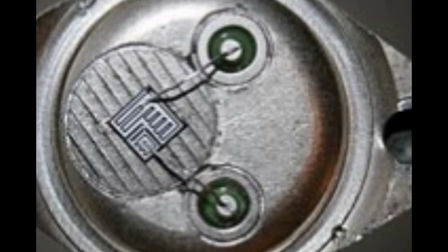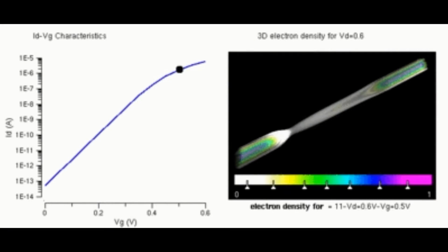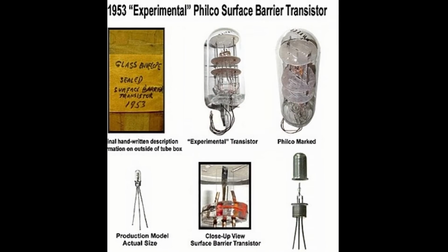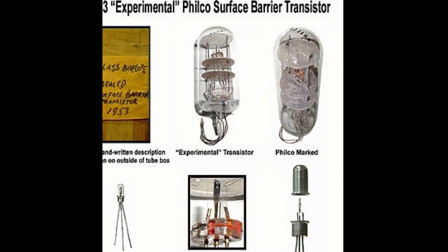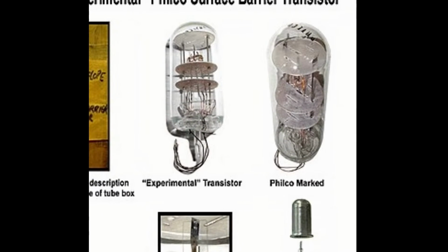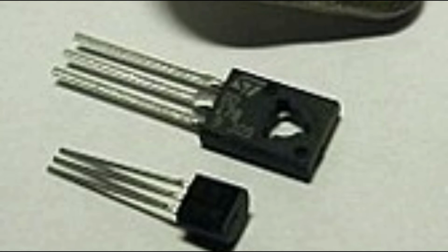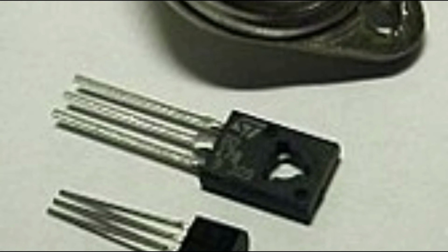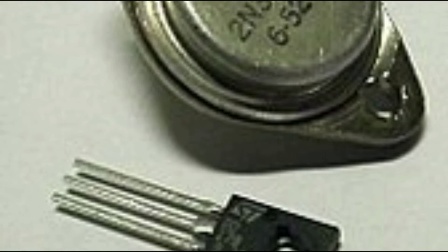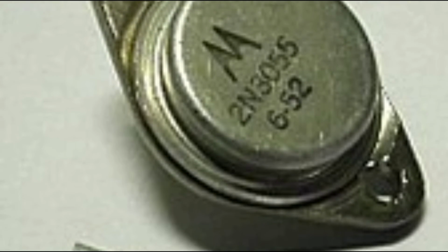There are 2 types of transistors, which have slight differences in how they are used in a circuit. A bipolar transistor has terminals labeled base, collector, and emitter. A small current at the base terminal can control or switch a much larger current between the collector and emitter terminals. For a field effect transistor, the terminals are labeled gate, source, and drain, and a voltage at the gate can control a current between source and drain.